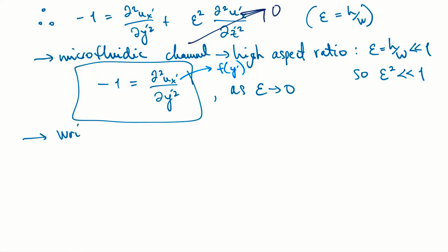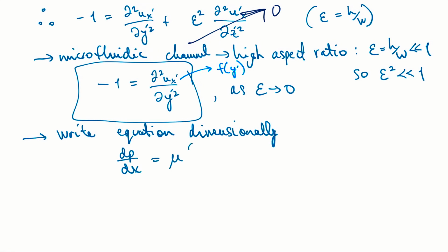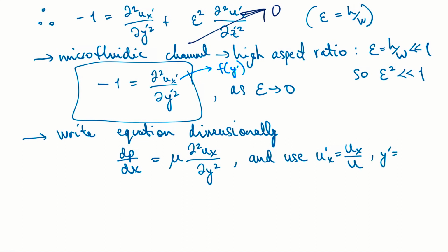And we're going to go back to our dimensional form. So I'll write this out dimensionally. Okay, so it would be like this. And now we're going to use a different non-dimensionalization. So we're going to use this here. We aim for some, usually average flow speed, so that's what capital U is here. Length scale. And then I actually need this X scaling just because of the pressure term there. Okay, so when I also go to scale my pressure, I'll scale it with the H as well.